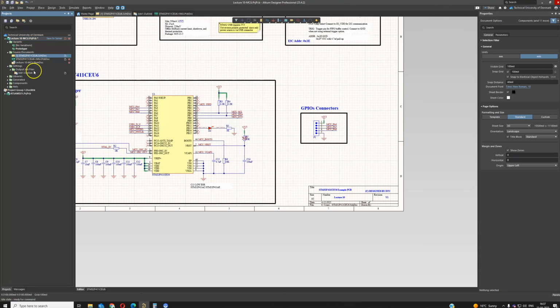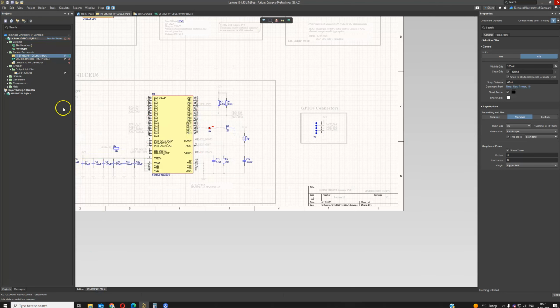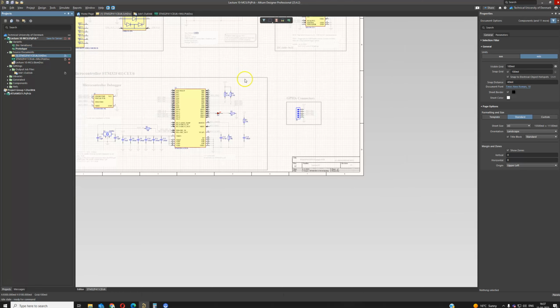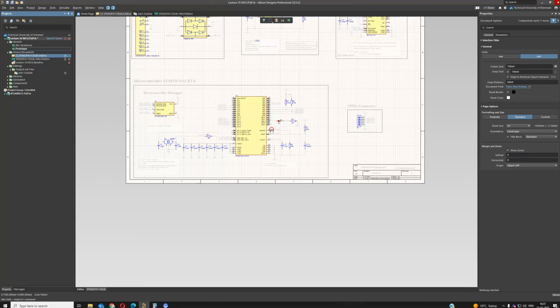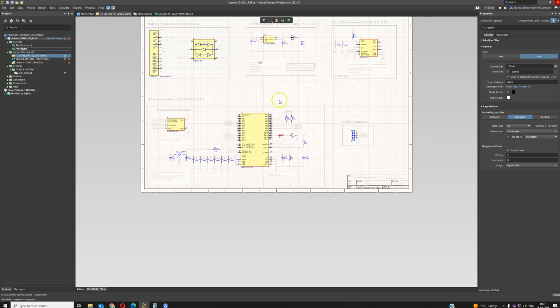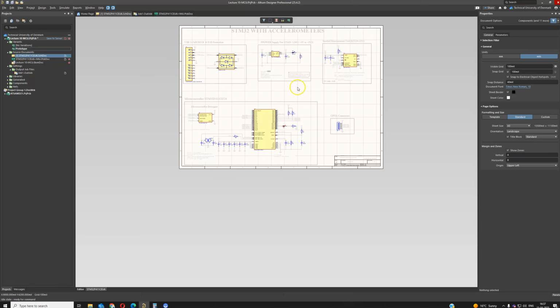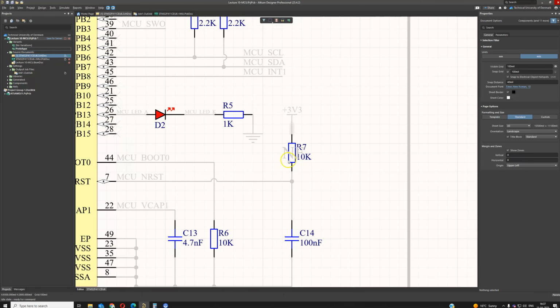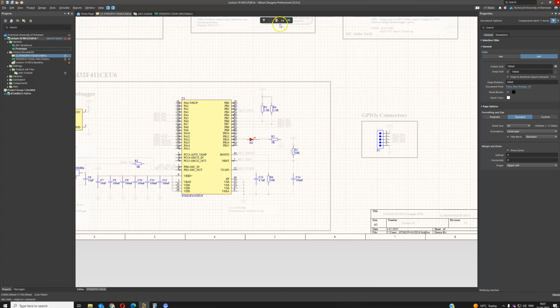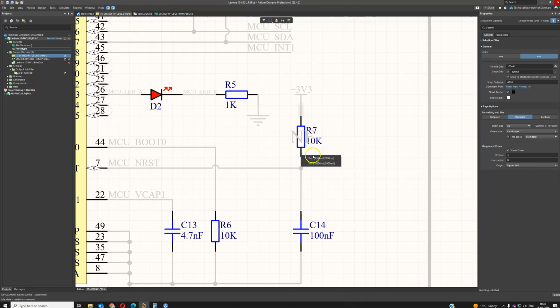So after this shows up, you go here and then you double click on the prototype. Be sure it's selected. So as we know, this variant helps us with the components we don't need to be in the bill of material files, basically. So we have this R7. I wrote an F, not fit, because I don't want to place it. Then I do here and then I click it, part.